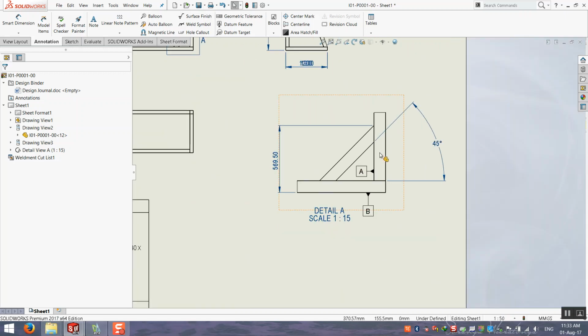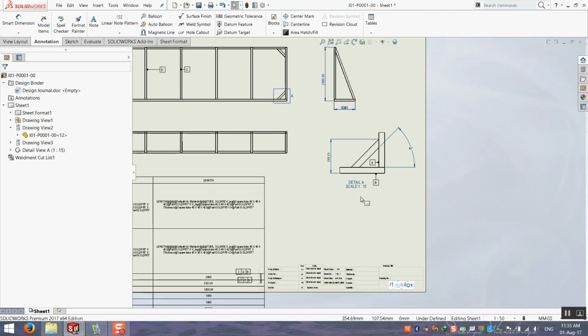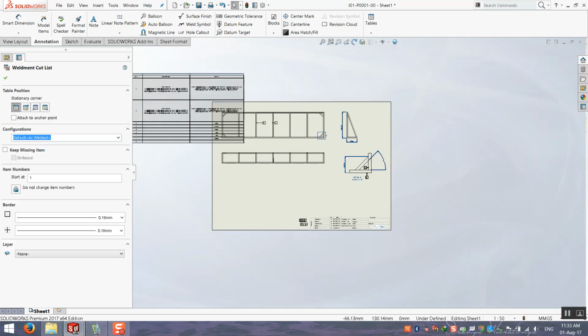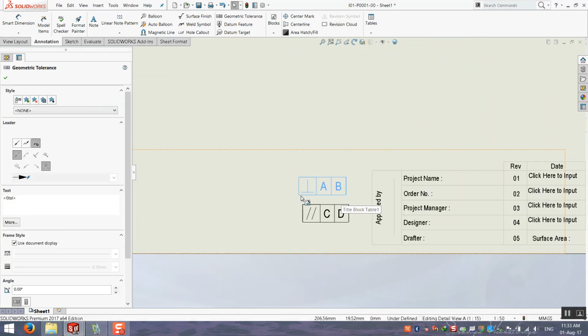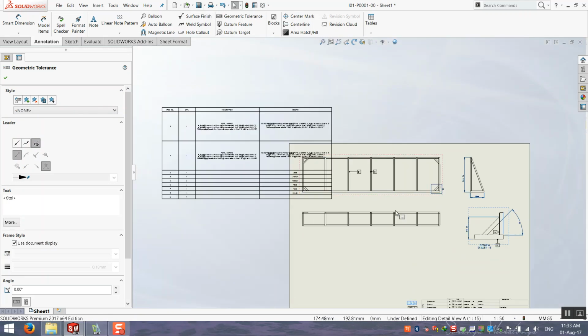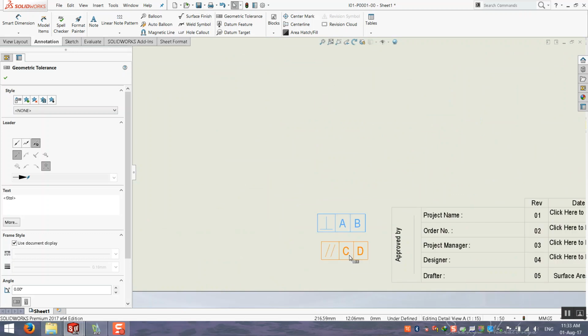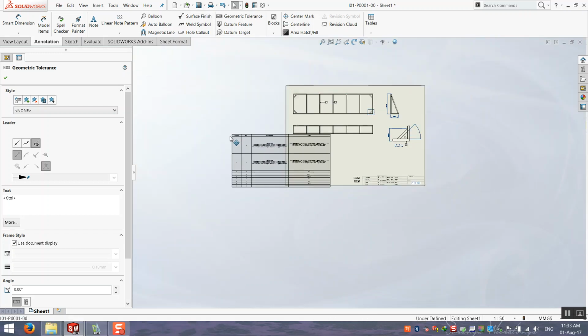It's for inspection. If I need this to be a right angle, after manufacturing you should make inspections. The inspector will see these signs A and B, and go to the notes in the drawing: A and B should be perpendicular. This selection, check, it's okay. Perpendicular, it's okay. C and D should be parallel. See this parallel, it's okay. Make a checklist for inspectors to secure your manufacturing.